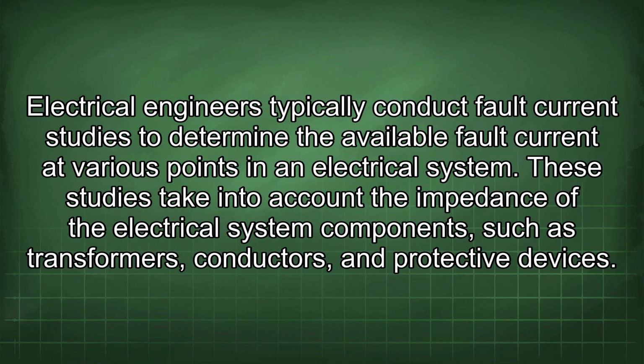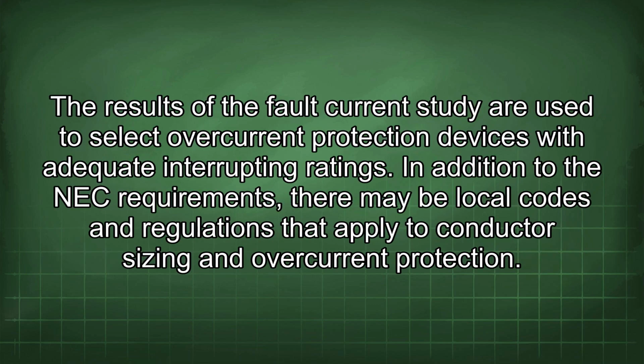Electrical engineers typically conduct fault current studies to determine the available fault current at various points in an electrical system. These studies take into account the impedance of the electrical system components, such as transformers, conductors, and protective devices. The results of the fault current study are used to select overcurrent protection devices with adequate interrupting ratings.